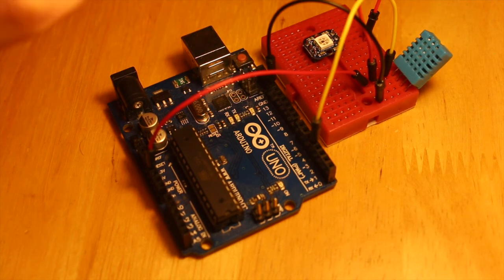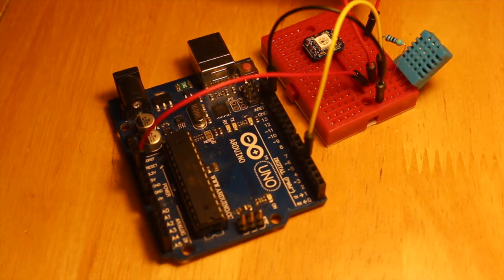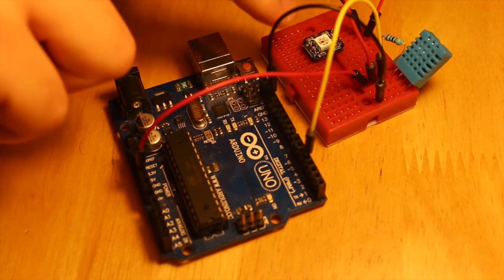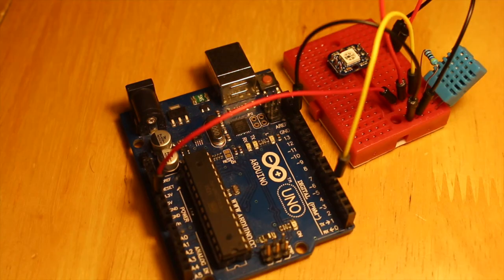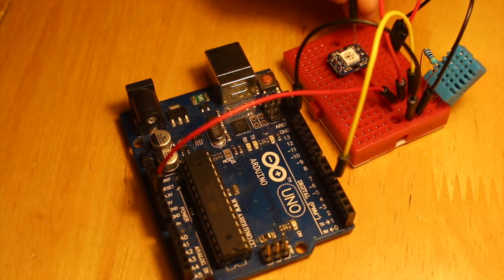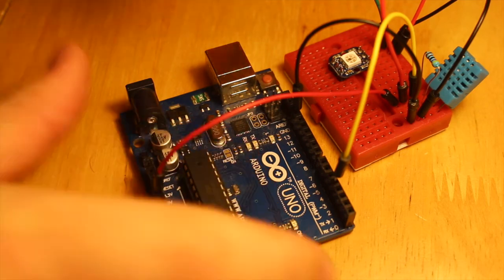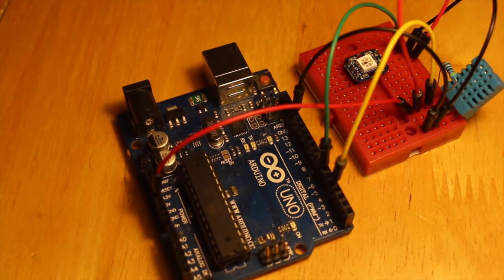We can't forget to add our resistor between the first and the second pin on the temperature sensor. So let's do it now. Let's connect our LED to the ground, which I can do the same way as I did with the temperature sensor, letting them all be in the same position. And lastly, let's connect the in pin from the LED to pin number 6 on the Arduino. Okay, it seems that we are ready to roll.